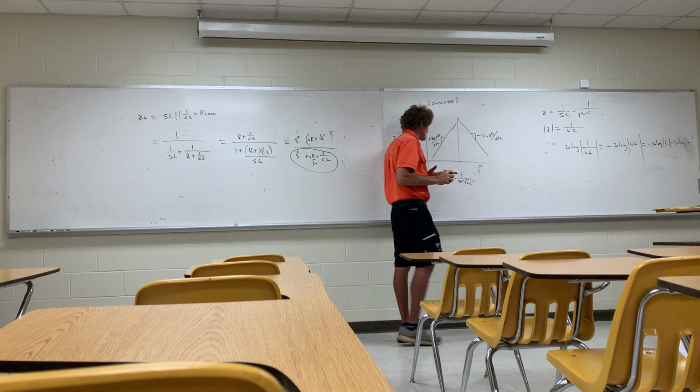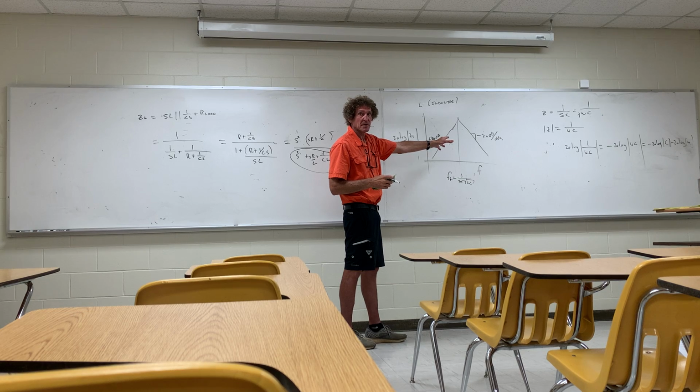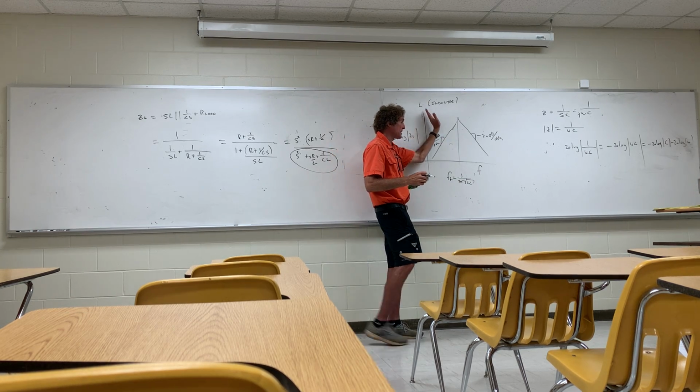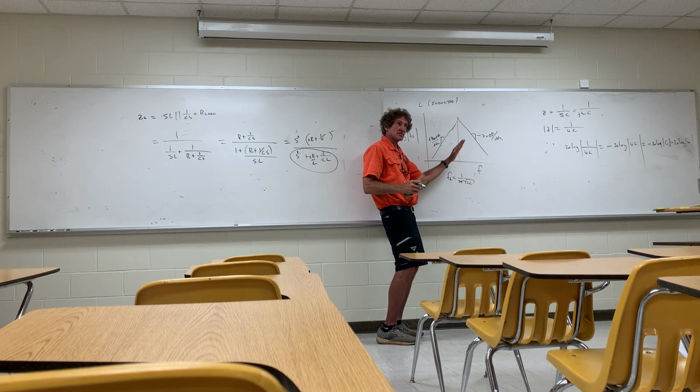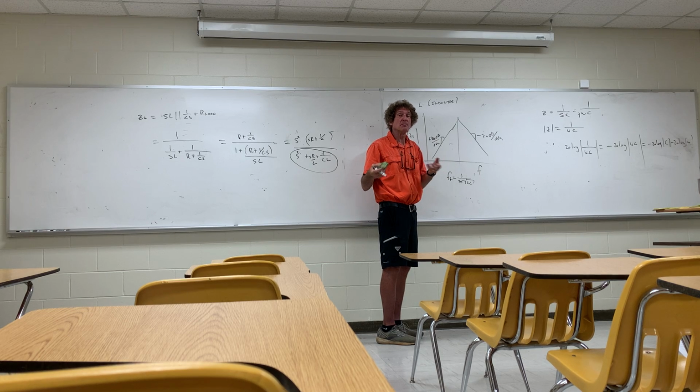Now, I'm going to mention one thing about this. This is the inversion of the capacitor's impedance, if you think about it. For a capacitor, it came in from infinity, hit resonance, then starts going up again, right? For an inductance, what's the impedance of an inductor at DC, ideally? It's zero, right? I mean, impedance is j omega L. If omega is zero, it's zero, right?